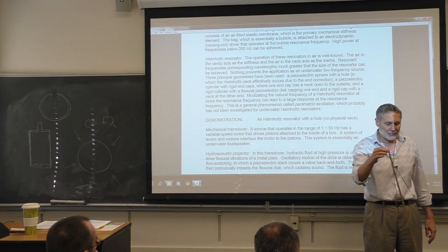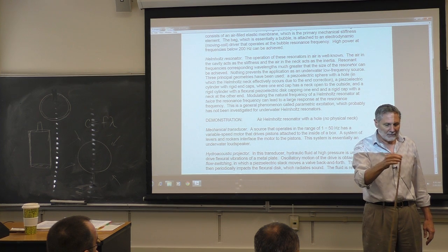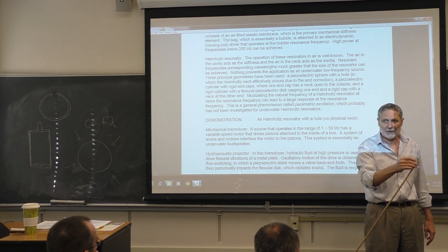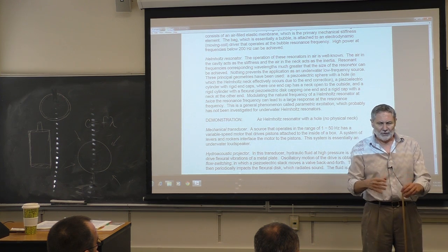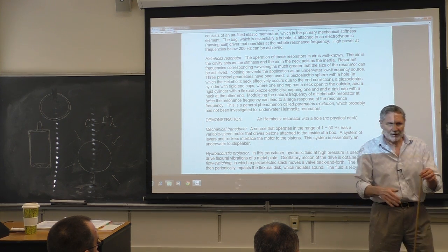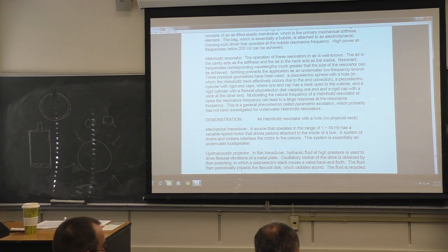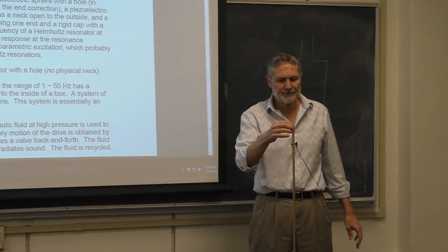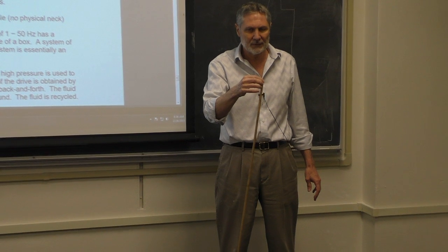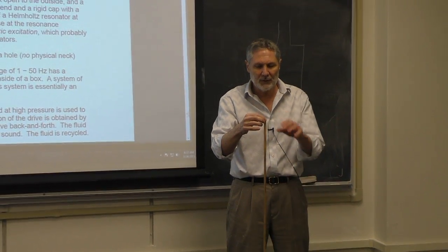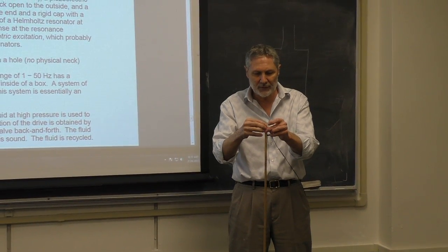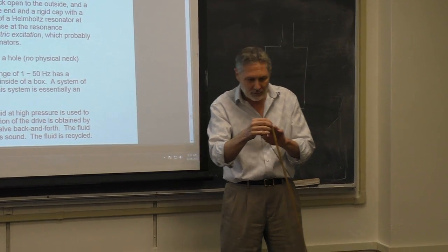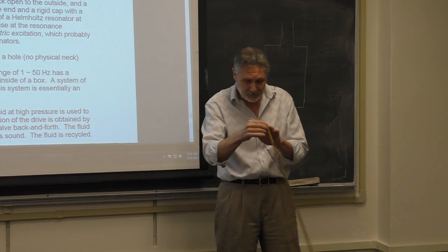If I drive the support back and forth, there's resonance, right? I can feel it. Okay? Now this is the standard one we call direct excitation. And if you want to understand it, we need to use Einstein here, believe it or not. We need to go into the frame of reference where the pivot is not moving, okay? So once you imagine going to this frame of reference, going back and forth.